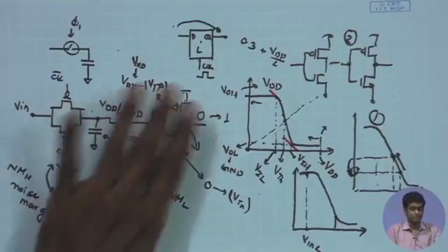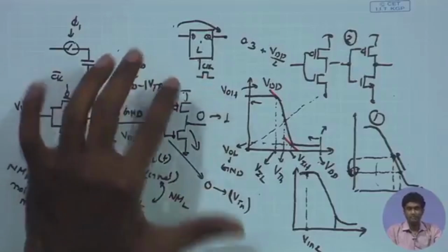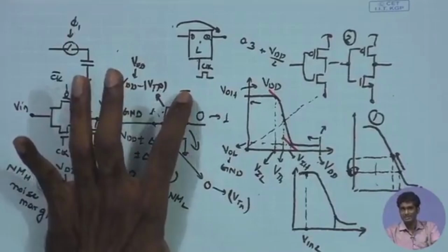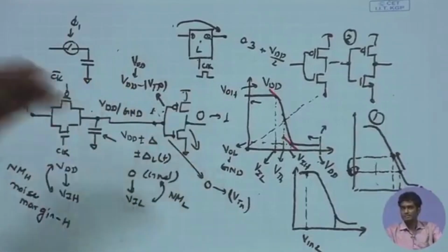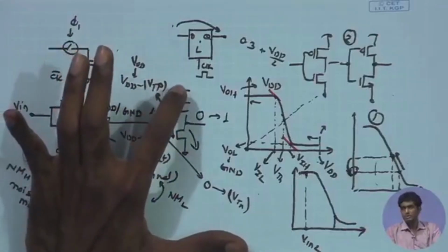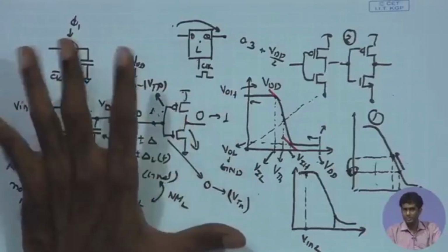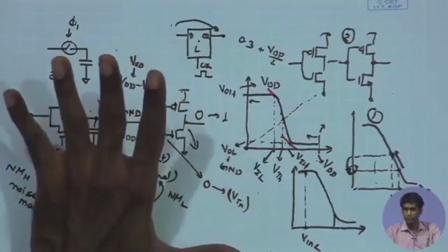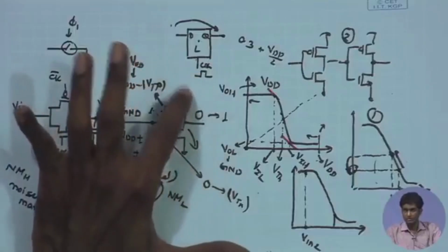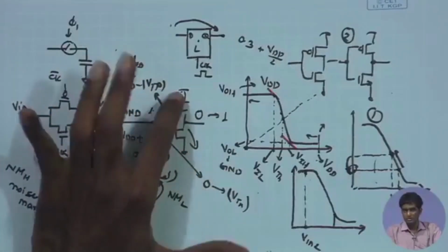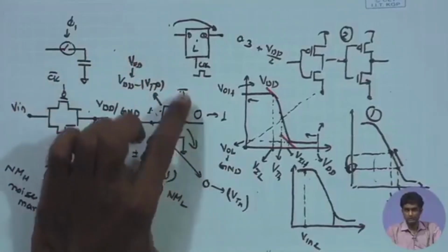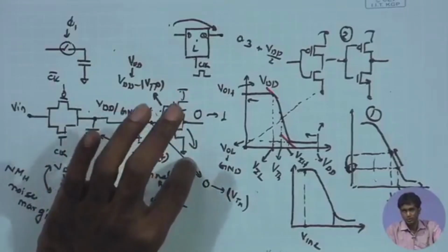So, in general, for the digital logic, you can have VDD which can be very noisy, you can tolerate few tens of millivolt, even 100 millivolt of noise in the VDD and ground, whereas in the analog circuit we can't even tolerate a millivolt. We have to make sure that the VDD noise is lower than a millivolt, very clean, microvolts of noise or disturbance, whereas in digital logic you can have much worse supply, much fluctuating voltages over here and here, few tens to 100 millivolt of noise is also okay.